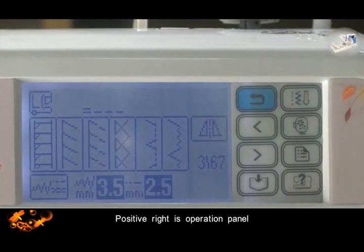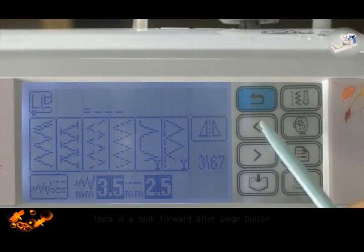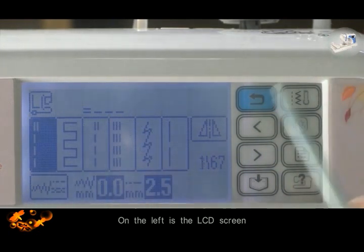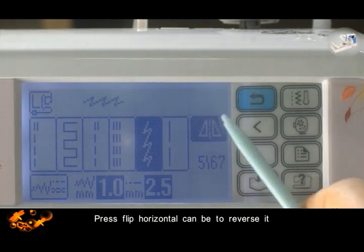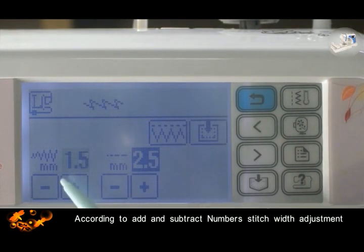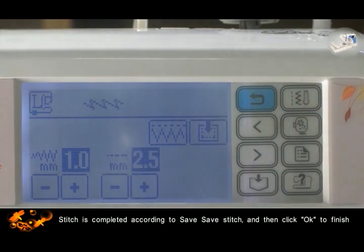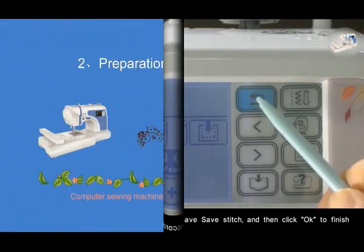Right in front is the operation panel. Here are the forward and back page buttons. On the left is the LCD screen. Select a stitch. Press flip horizontal to reverse it. Enter the stitch width adjustment, pressing add and subtract to change the numbers. Stitch length adjustment works the same way. When the stitch is completed, press save stitch, and then click OK to finish.